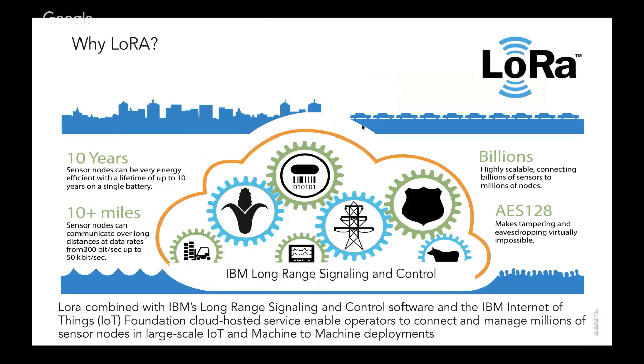Essentially, one drawback compared to other protocols like Wi-Fi and Bluetooth is that the payload for LoRa packets is very small. You can send about 100 bytes per minute. That works for small sensor values and small text messages, but that won't really work for large data payloads like images and audio.